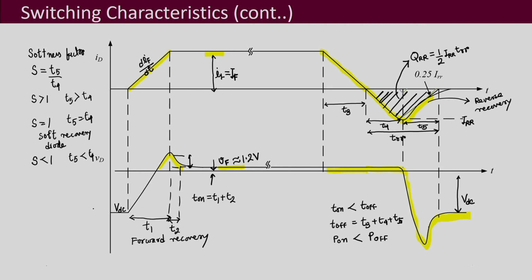What it means is that the diode voltage just snaps off here. So this is VD while you are turning off. It just quickly settles down to the voltage VDC. In that case, you have a high overshoot transient, and this is usually a faster recovery diode. And in that case, it can also be called a snappy diode.